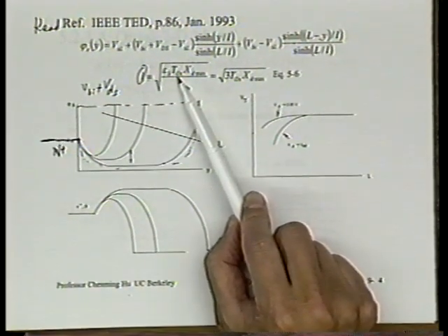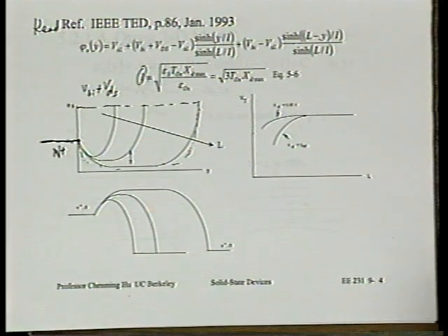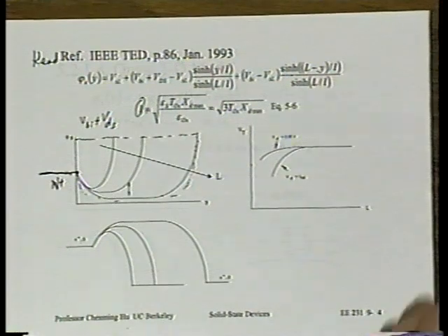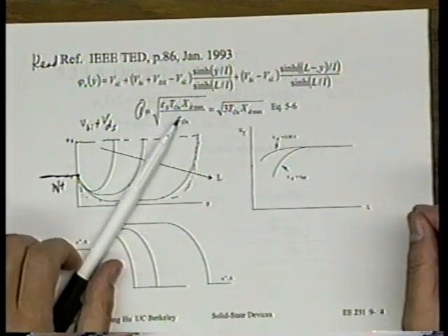Thin oxide. See? That's the same result you will get from the charge sharing model, but it's a totally different way. In the charge sharing model, the oxide thickness comes in just because the charge is divided by Cox. But here we show you that the whole profile of the potential is intricately linked to Tox. Makes sense.